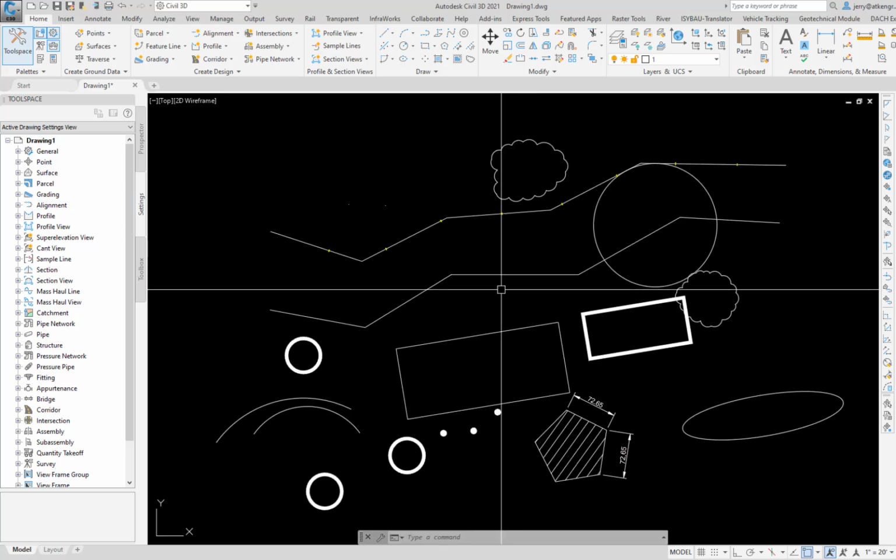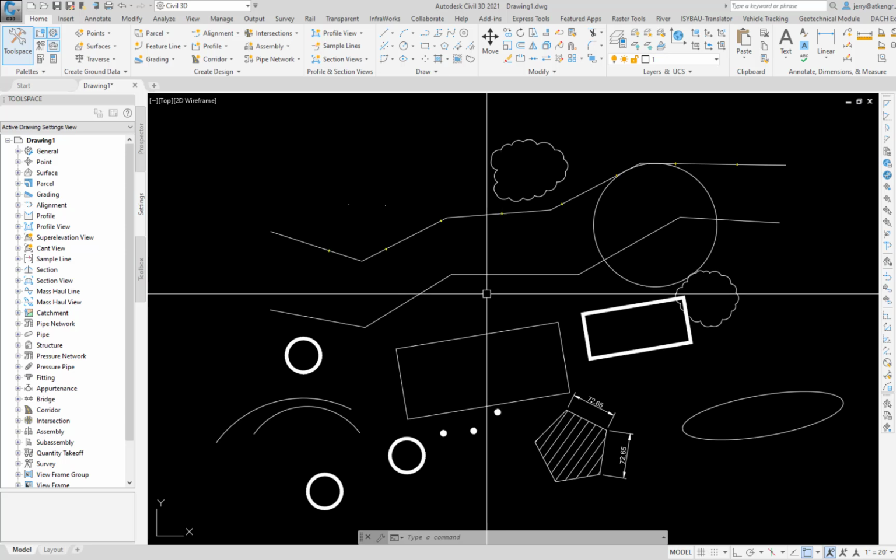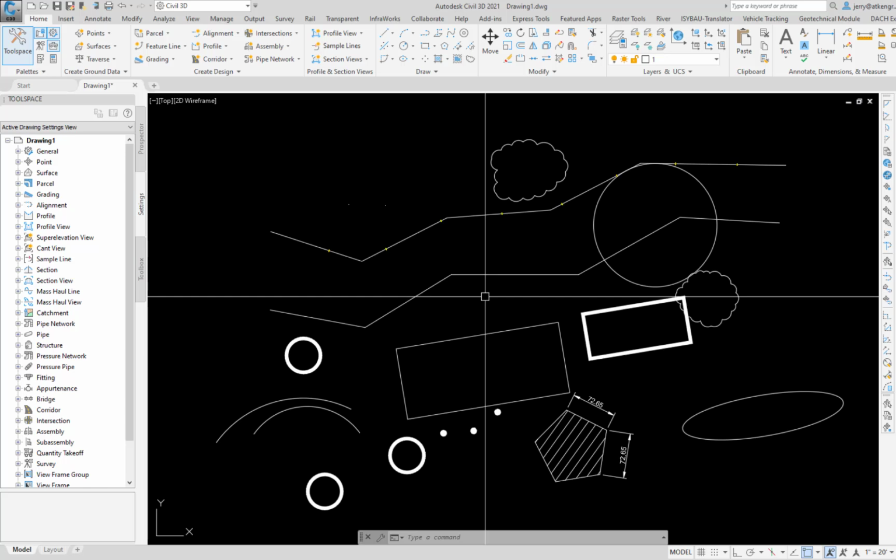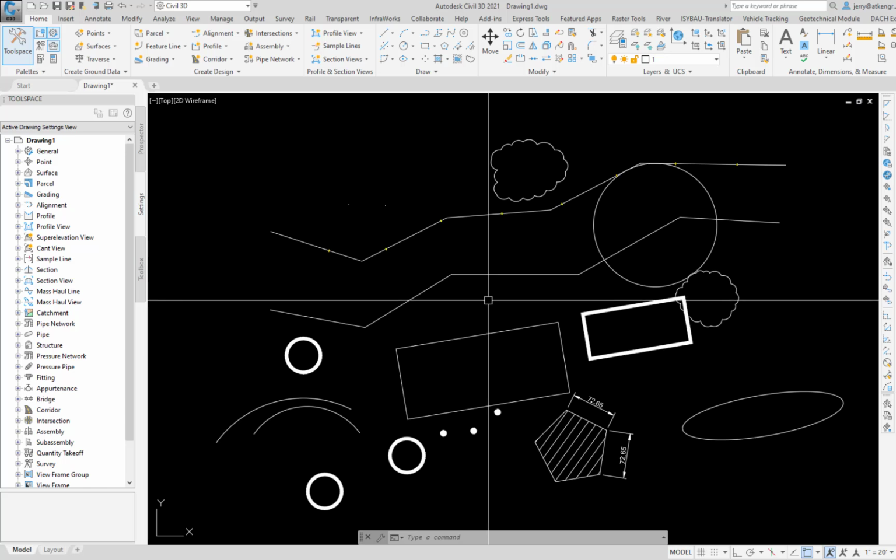For illustration purposes, this line is assumed to be an alignment in which the left endpoint is at station 26+85. It is desired to determine the station and offset distance of various points relative to this alignment. In order to accomplish this, set the origin of the UCS coordinate system with X and Y equal to 0 at a desired point.